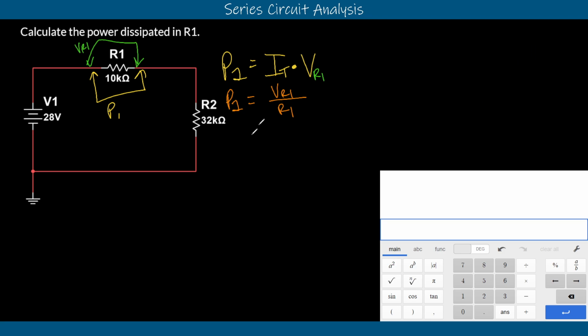So our voltage divider equation is quite handy. It is a ratio equation, and it identifies where voltage drops in the circuit. And so some voltage will distribute across some resistors, and the rest of the voltage will distribute across the rest of the resistors. And by the end of the circuit, down here at the bottom, we should have 0 volts. We should have used it all up by the end. And so we're going to do that using our voltage divider.